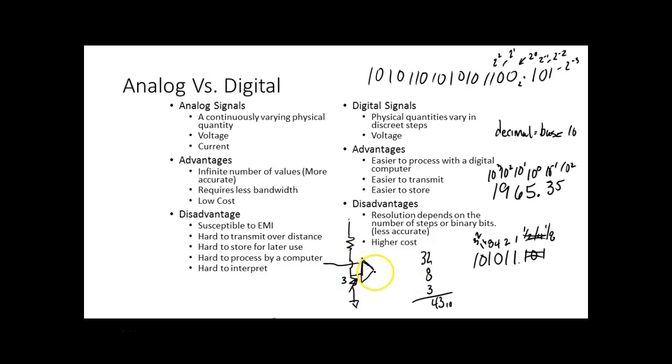So if I set this at 3 volts, then no matter what the input is doing, as soon as it exceeds 3 volts, the output would go true, whatever true is. Let's say it goes to 1. So these guys are going to have to be powered up, right? Does that make sense? And when it comes down and drops below 3 volts, the output should drop to a digital 0, or whatever that is. Now that's going to be a voltage level, right? You understand that? These devices are called comparators. They've been around for years.